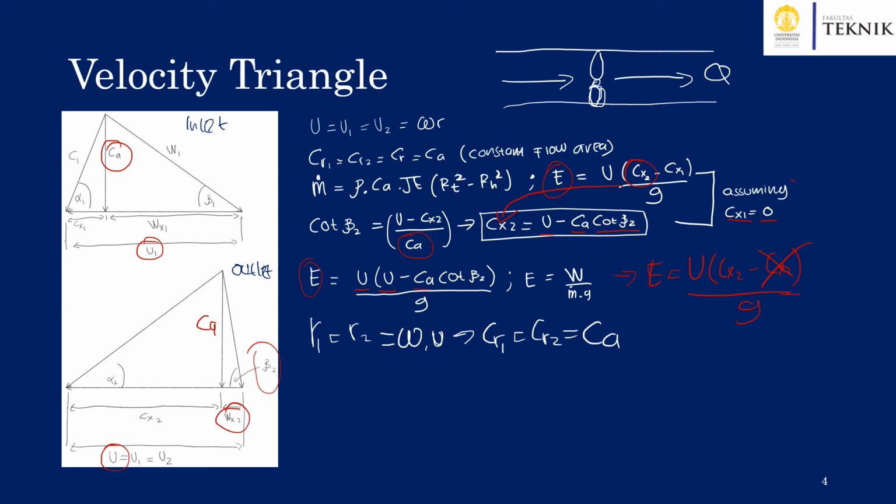When we compare back to the centrifugal pump, we have a difference in U, or blade velocity, between inlet and outlet due to the increase in the radius of the impeller. But in an axial pump, as the radius of the impeller is constant between inlet and outlet, the difference is only, if we look from the front, where the blade of the impeller looks like a fan, in the tip radius and hub radius.